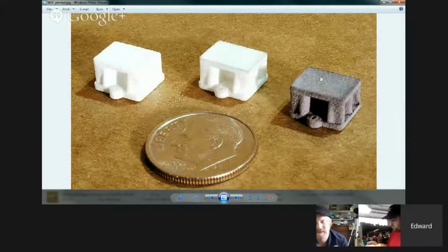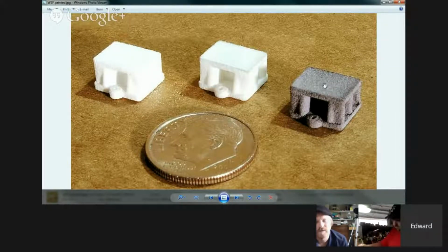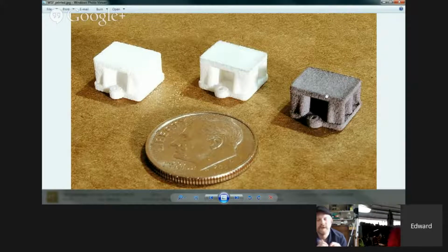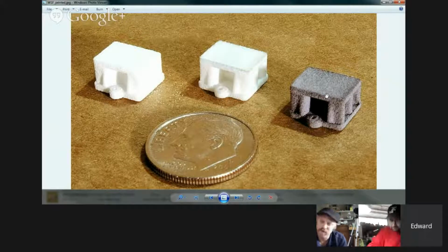Yeah. And you asked me, well, why would you use this in preference? Because I could stand on this and it wouldn't break. Oh, cool. Okay. That's a big plus. This is more like a Delrin, like your black slippery plastic. It's more like that. It's not as smooth, but in strength, it's similar to that. So FUD is a better material for model railroading because we don't really sit on the layout ever.